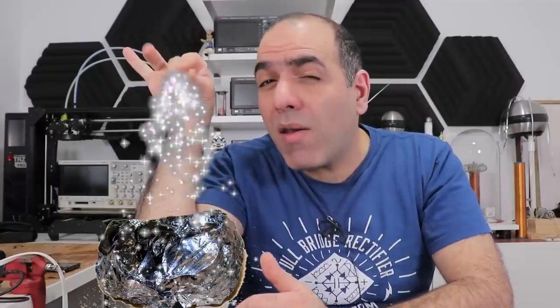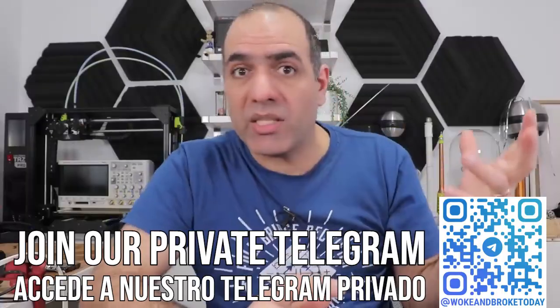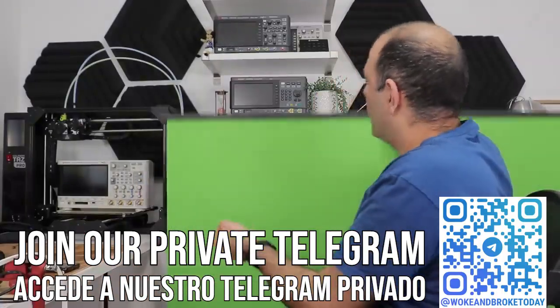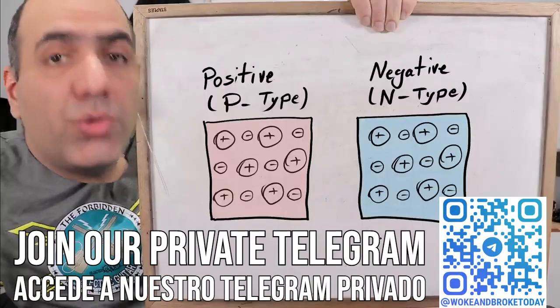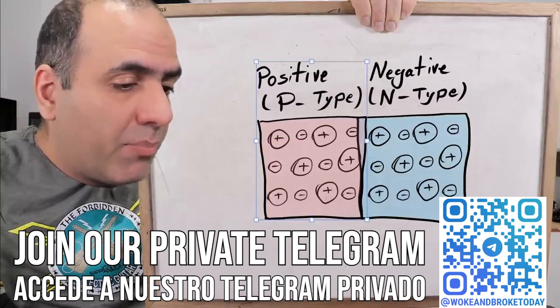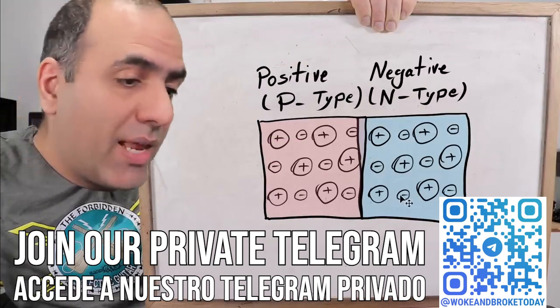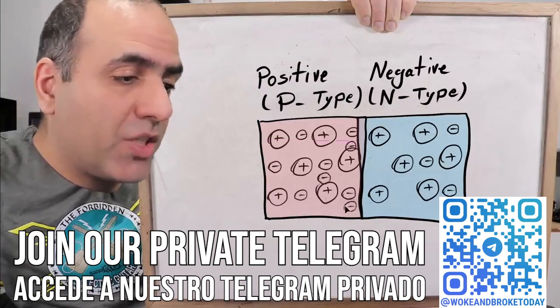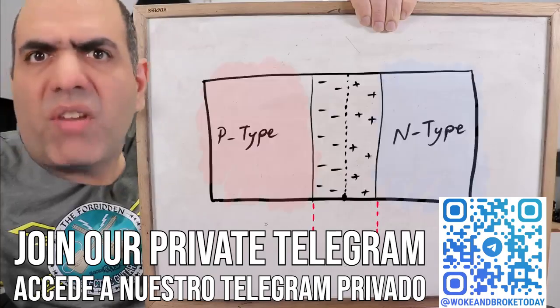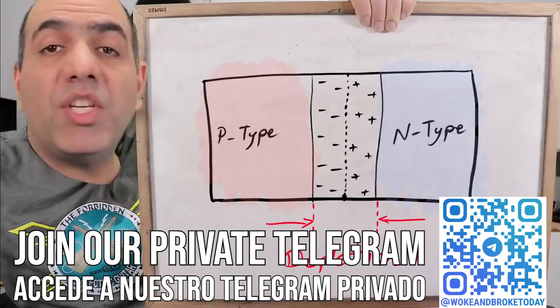Semiconductors are material typically made of silicon crystal that we dope them with small amounts of impurity. And depending on the type of impurity, we get positive or negative semiconductors. As their name suggests, they are conductive. They are electrically neutral, of course, but if we fuse the 2 types together, the p-type will happily pull electrons from the n-type, which is happy to give them, right at the junction. This creates a small region of charge imbalance called depletion region.